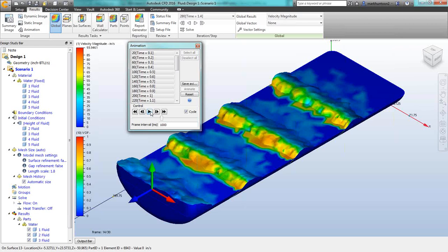And I could pause and take this time step and then go into Simulation Mechanical for this tank and turn off the fluid. Kind of funny that I'm turning off the steel for CFD and turning off the fluid when I go into Sim Mech, but I can actually pull these pressure forces from the water into Sim Mech and run my analysis. So it's a very, very powerful feature, and it's something really neat to show off to your boss. So it makes you look like you're really working hard, which is what we all want.